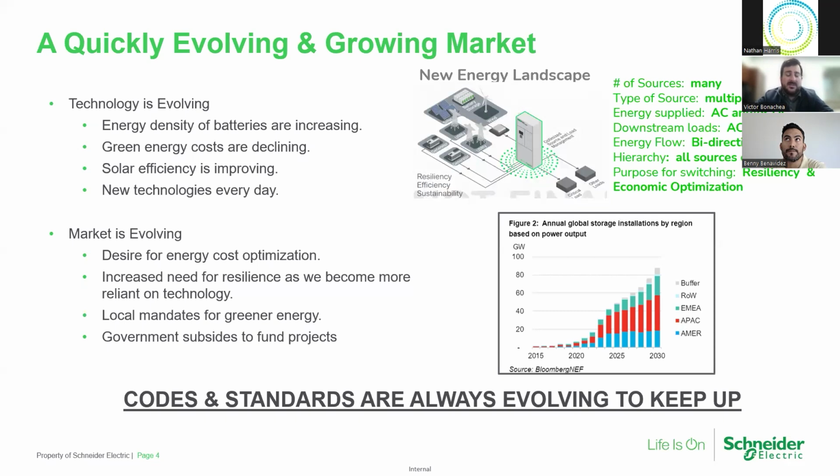And with that, some of the sequence of operations and the way you design these systems has to change to account for the dynamics that brings into the picture. Not only that, but some of these sources that we're seeing are resulting in energy flow potentially being bidirectional. In the past, it used to be very top-down, hierarchical kind of way the power flowed from the top where your source was down towards your loads through your distribution. But as we're starting to see solar that could be on a panel, or battery energy storage, which sometimes it could be a source when it's producing power, other times it can be a load when it's charging. That's causing power to flow in both directions now in our electrical system, which is further changing dynamics of these systems and things that are going on out there.